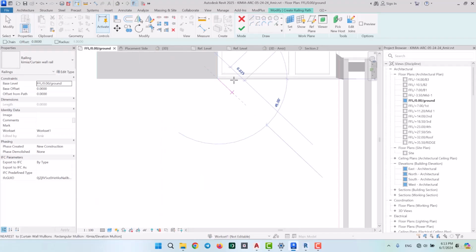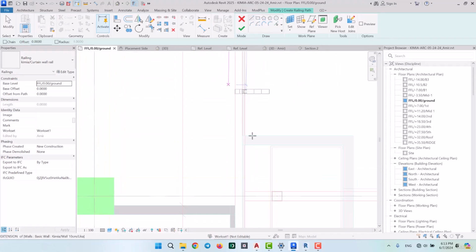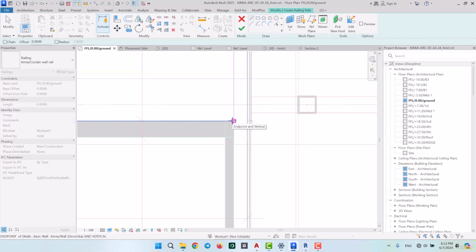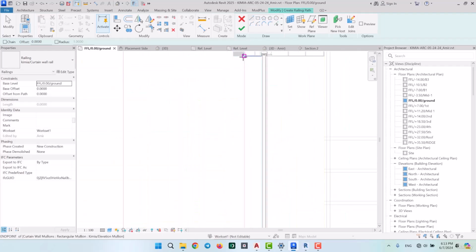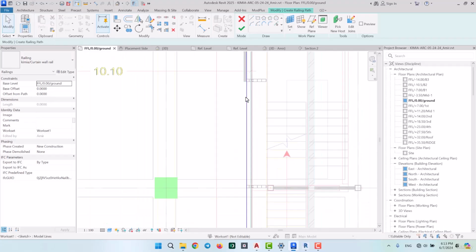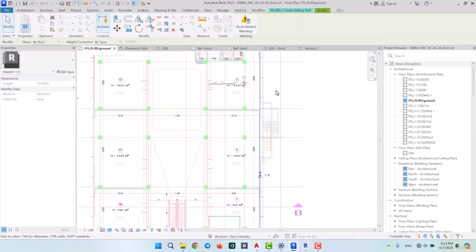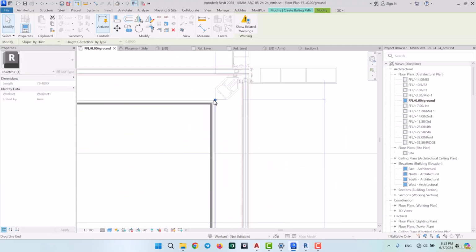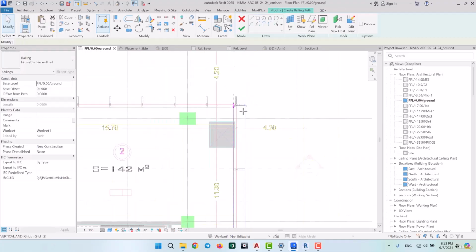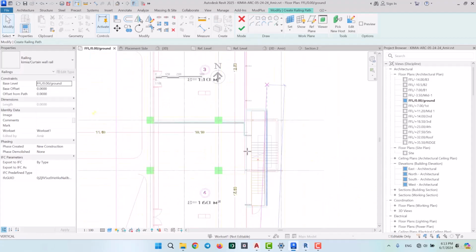So it goes from this point all the way down to here, and looks like I'll have to pick lines and then pick this line to draw over it. Only we might have to adjust the position of both ends. Basically, it would be a lot better and more precise if you try and draw these railings manually than to do it by using pick lines.